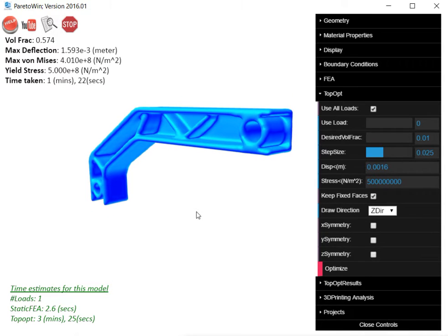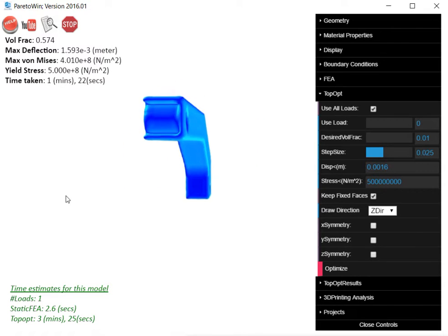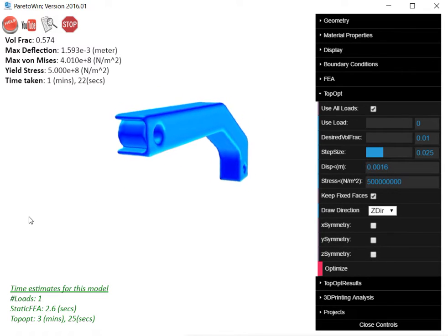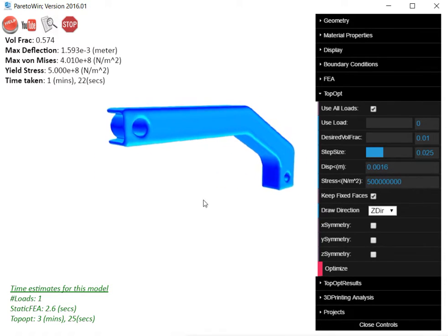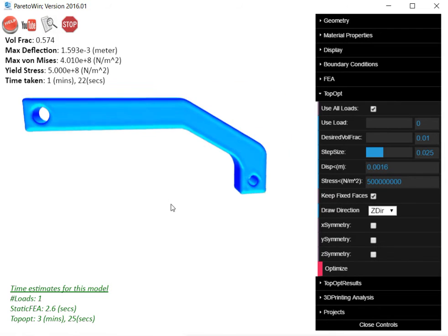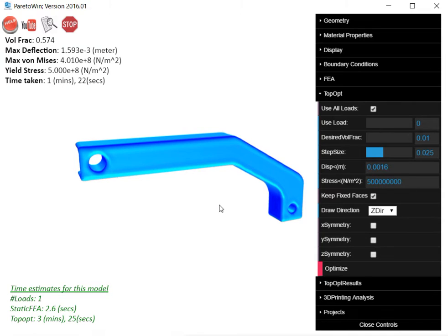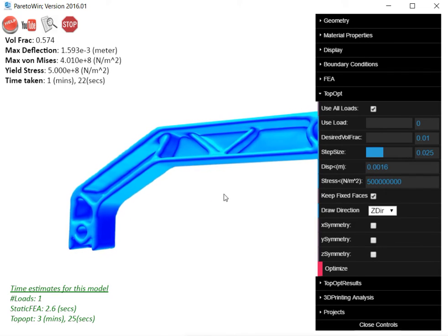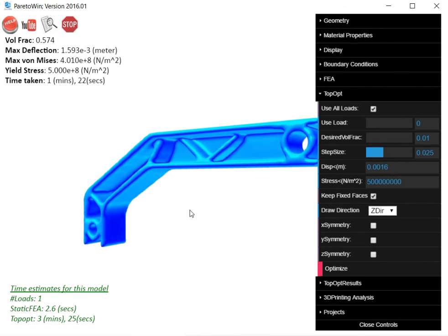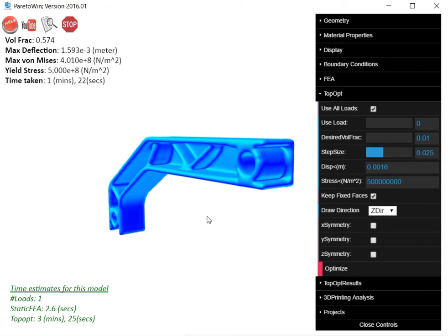The topology optimization is complete, and you'll find that the topology optimization is in fact very different from what we found in the previous two topologies. And in this particular design, you'll find that you've retained the faces from this direction. From an aesthetic perspective, this might be desirable, and it creates rib structures on the inside to result in a different topology of a different volume fraction. And this concludes our video on design constraint topology optimization.